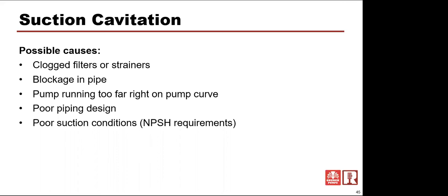What they think is a good idea to save energy, they haven't accommodated for the lack of back pressure. The proper thing to do there, if they wanted to do that, would be to spin this thing down with a VFD, run it at a slower RPM, perhaps, depending on the system, where the pump is not trying to put out as much pressure. It changes the pump curve, it drops it down, and therefore our NPSH drops because we're not trying to move as much fluid, and all of a sudden we save energy and help the pump run. So suction side cavitation, those are generally your common causes for it.